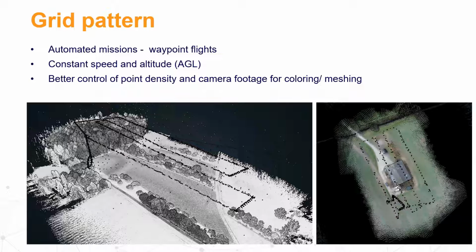In general, the recommended speed or height does depend on the project. One thing to have in mind is that you shouldn't be more than 40 meters away from the features, and something smooth like 5 meters per second or less for the flight speed, and maybe up to 50 meters flying height. You can use that to create your flight patterns.